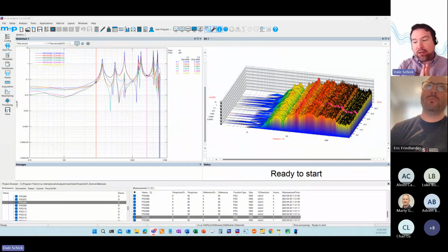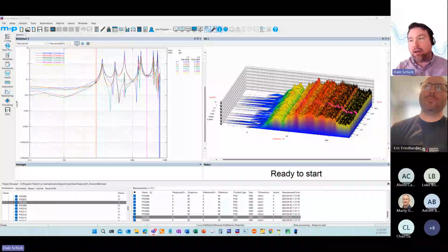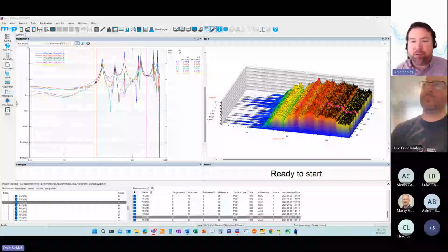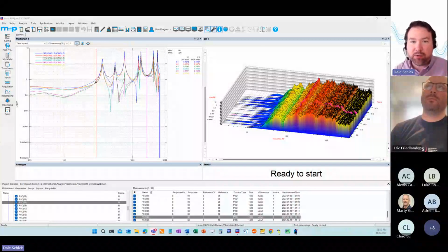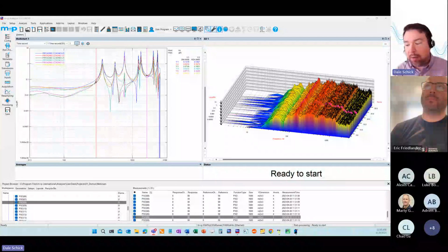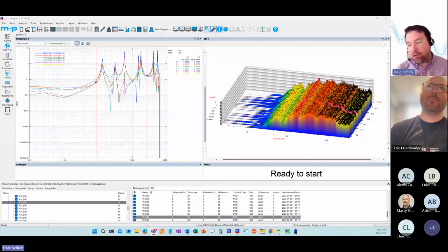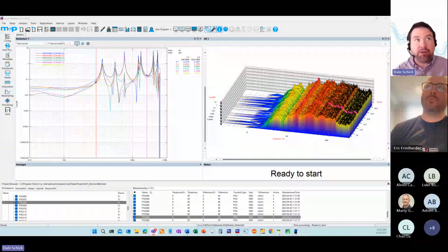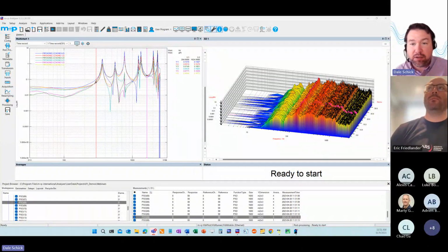The higher the fractional division of the octave bands, the closer you get to narrowband, where you're kind of isolating yourself to only being able to control high frequencies really well and characterizing them really well. So we've tried to find a happy medium between 1/3 octave and one octave processing for acoustic. And so far, most of the launch vehicle manufacturers that I know of have just specified it in third octave as a result. One, because that's how they measure it, but two, that's how it's typically defined in the process. But it is a great question.